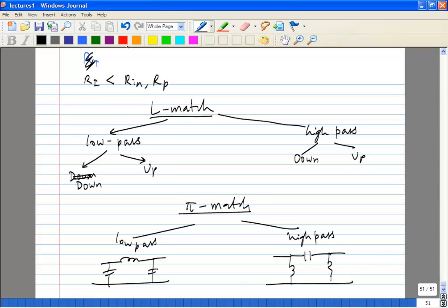Remember, inductors are huge. In any IC process, for typical values, so we are looking at the values, right? You're getting a few nanohenry and a few picofarad. A few picofarad will probably consume a few tens of square microns, whereas if you get an inductor which is a few nanohenries, it will occupy a square or a circle which has a diameter of, quite often, anywhere from 150 microns to, if you want higher Q, you might want 500 microns, something like that.